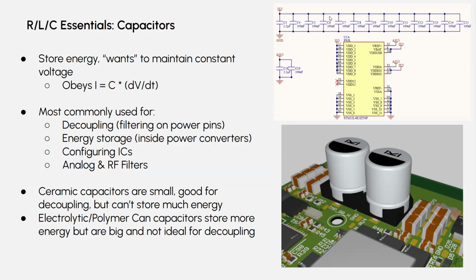Ultimately, what this comes down to is you put capacitors on all your power pins, just between ground and power. And what this means is that it smooths out the voltage waveform nearby, and you really want these to be as close as possible to the pin physically. We'll cover this more when we get into Altium in terms of the actual physical layout, but generally capacitors are a very location-dependent thing of how effective they're going to be, especially at small values.